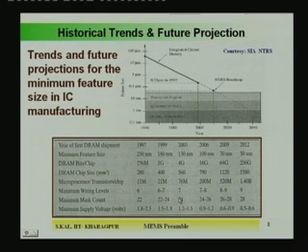That means, at present in all the microprocessor chips, 7 or 8 levels of metallization are being done, and if the number of levels is more, the technology is getting much more complicated. Obviously the yield is another important point, which is another yardstick. So, how good your technology is, how commercially viable it is, etc. So, yield should be very good.